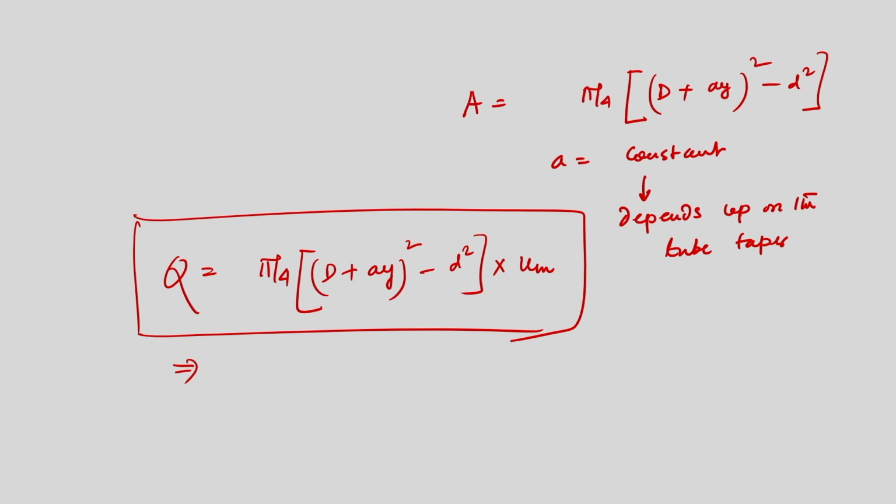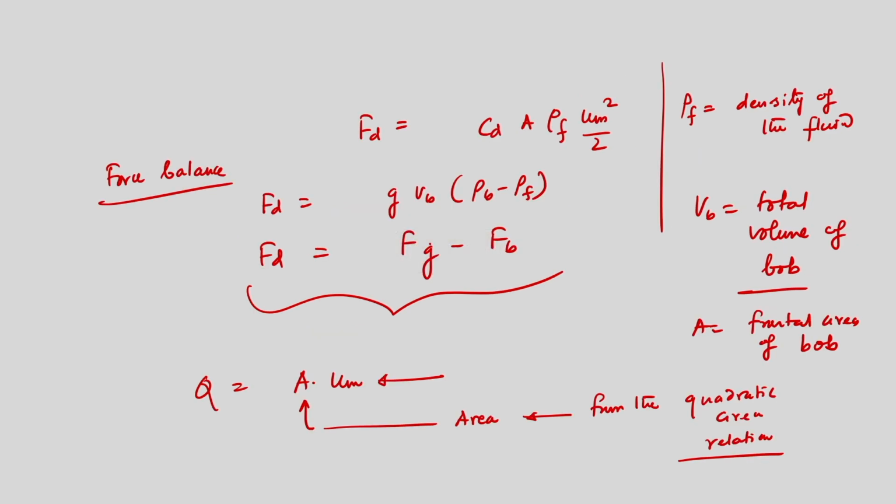Here are a few important things that I will discuss now. When the flow is taking place from the bottom, there is a flow velocity, and that flow velocity will try to drag the bob along. How far it drags the bob depends upon the strength of the flow velocity. As I said, the position of the bob in the tube is an indication of the flow rate.